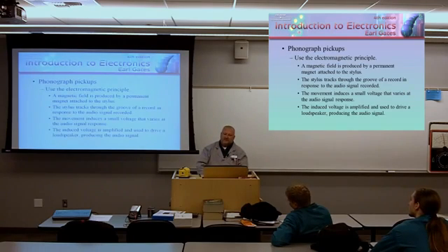Phonograph pickups. I'm sure some of the younger students are sitting in here saying, what is a phonograph, right? What's this with the scratching? That's what they're scratching on, a phonograph. It uses an electromagnetic principle, believe it or not. A magnetic field is produced by a permanent magnet attached to a stylus. The stylus tracks through the groove of a record in response to the audio signal recorded.